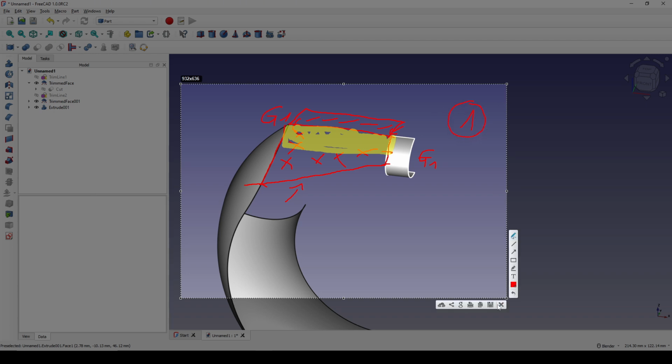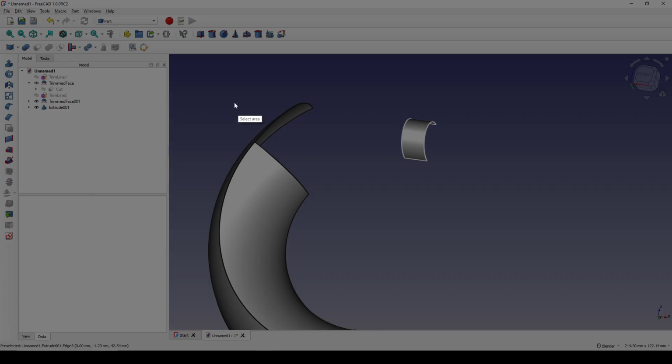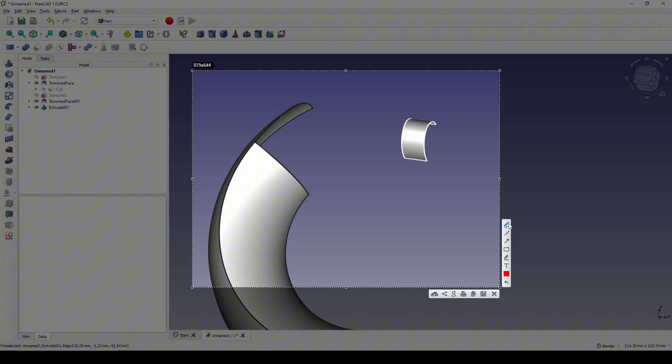Okay. And to create the second piece, I'm doing the same. I cut another one in here and another one in here. And then I will use the plane curve, 2 plane curves. And for this plane curve, I will extrude this one out a little bit to create a support face, the same.